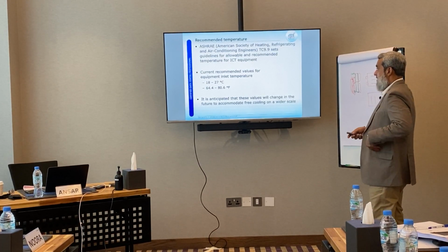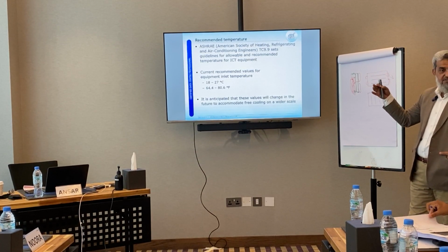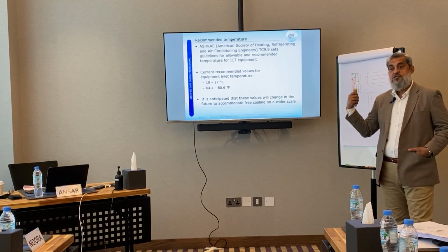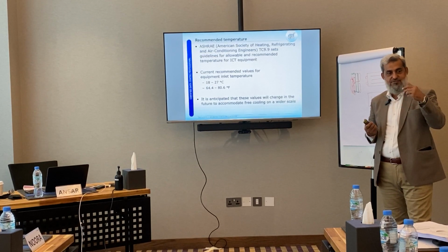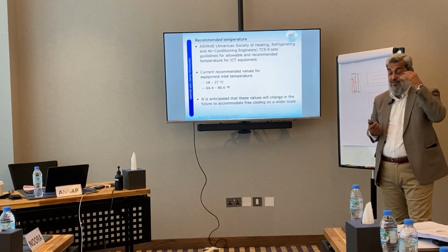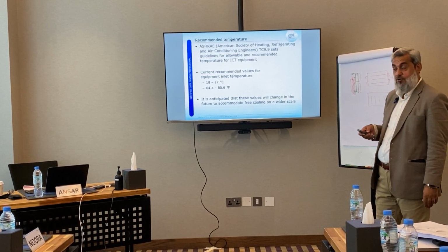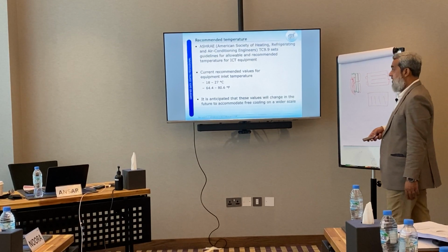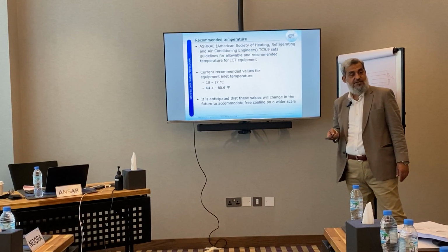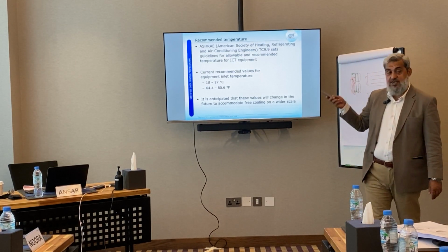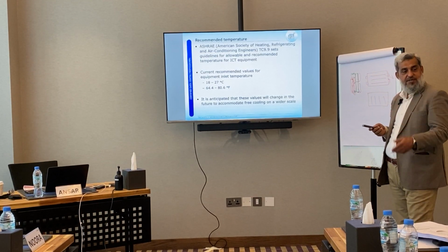ASHRAE is the American Society of Heating, Refrigeration, so it is a global standard. As I said, we discussed yesterday standards for the subcomponents. So every component, like for the fire systems, for power, electrical systems, and similarly for HVAC, we have a global standard, the ASHRAE guidelines, and they have a committee within ASHRAE. TC 9.9, called Technical Committee 9.9, sets the guidelines for the allowable environmental parameters for the data center,